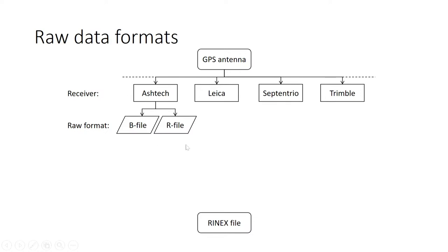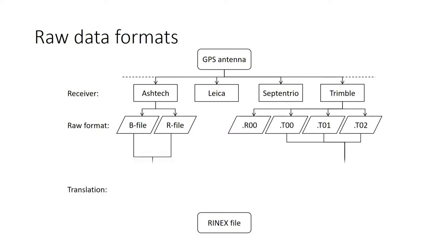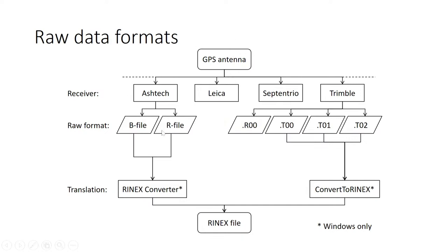So you can see you have to do the preparation, like this. There are different agencies providing instruments for GNSS data collection. Leica is there, Trimble is there, Septentrio is there, Ashtech is there, and some more manufacturers who provide the antenna and the complete instrument. And then you can convert to RINEX, and RINEX's full form is Receiver Independent Exchange Format. So this is the standard format to process the data in any software. So this is how you can do this.